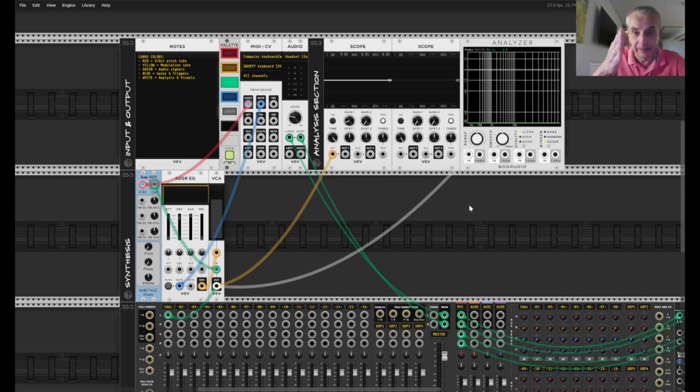And mathematically, the time that it moves from the upper part of the ramp down to 0 again, or whatever the starting value is, if that time is unlimitedly small, it means you have a discontinuous step in the function of the sawtooth, and therefore it means you need an unlimited amount of sine waves to actually reproduce that jump, and therefore your signal is not band limited and you cannot reproduce 100% correctly by sampling, or let's say adding sine waves in some way, shape or form.